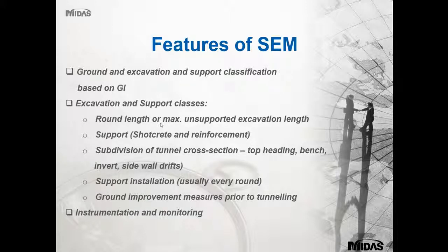The type of structural supports also depend on the ground type, be it rock bolts or Rockbox and Shotcrete, which are used in strong to soft rock types of ground, whereas steel ribs and lattice girders with Shotcrete or cast in place or concrete segments are used for mixed ground to soft ground situations. For tunnelling in competent rock, even full face excavations can be achieved, but in soft ground conditions the excavation phase should be subdivided into heading, drifts and invert.